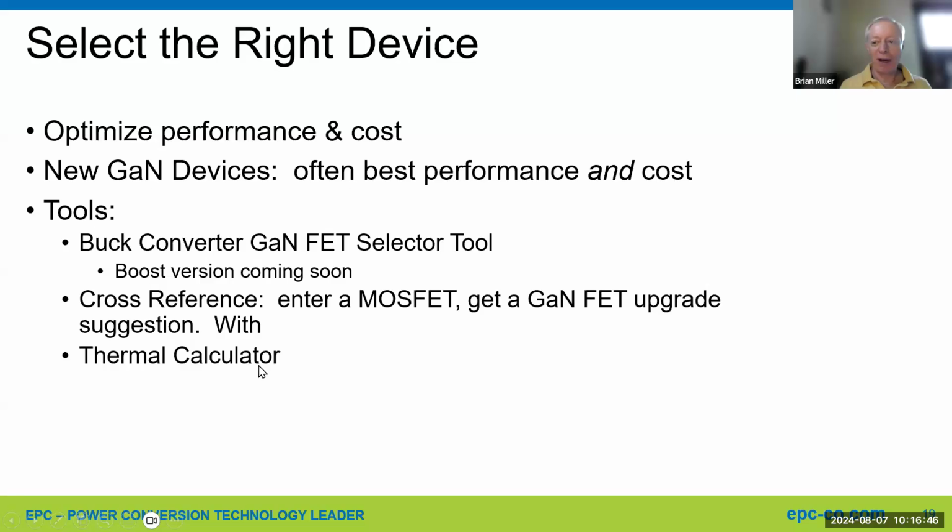There's also a thermal calculator, and that's really interesting. You can see the difference. Do you need a heat sink or not? Can the heat conducted into the board do well for you, or should you put some kind of heat spreader or heat sink on the top? So these tools are very good to select the right device for your particular application.